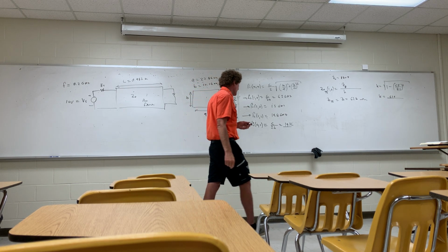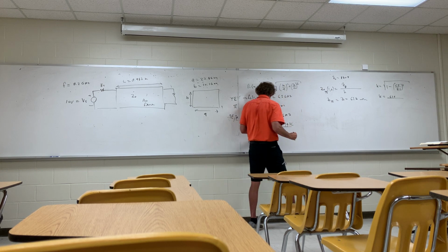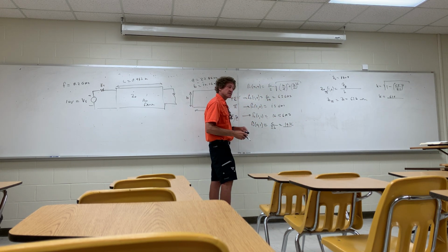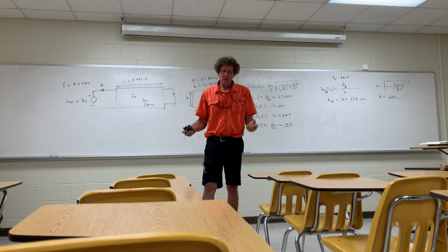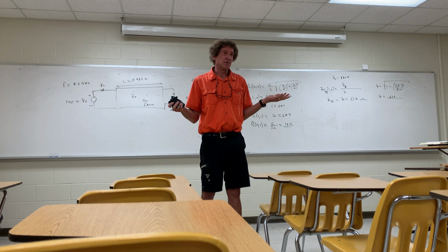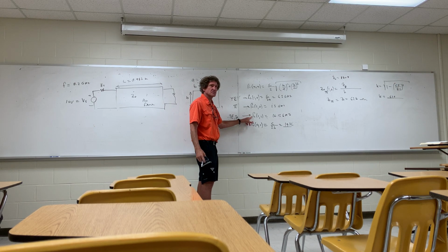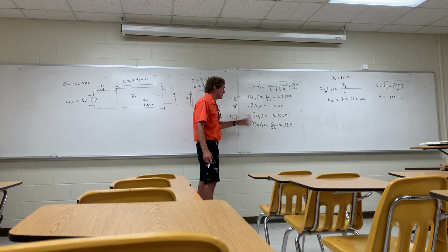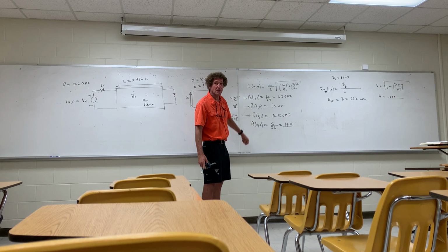For the 1-1? Yes, sir. Okay. 16.15 gigahertz, which means the modes would be this, and then this. All right, yep. So, like on a test, should you do all 4 of those modes? Normally, you can check them and just pick the lowest 3. Okay. But if it's a double mode like this, some people will say, well, that's 2 modes there. Yeah, it is. But just, you know, the lowest, say, 3 frequencies of propagation would be this, and this for that one. It would be the 01 mode, okay?